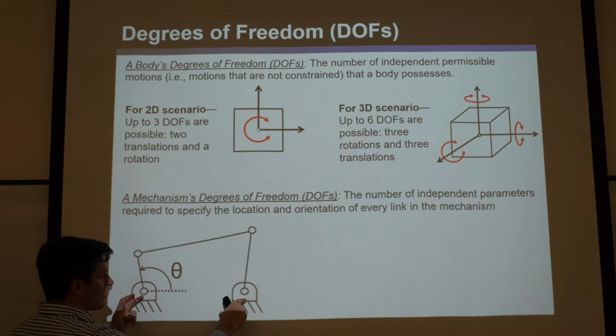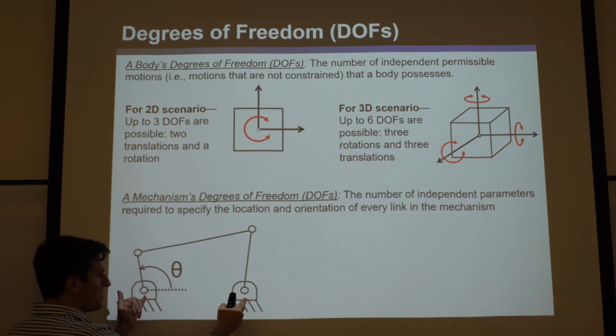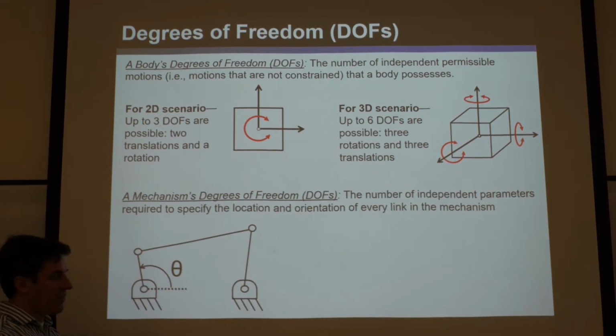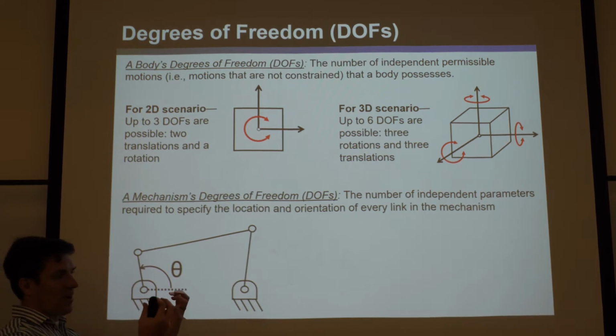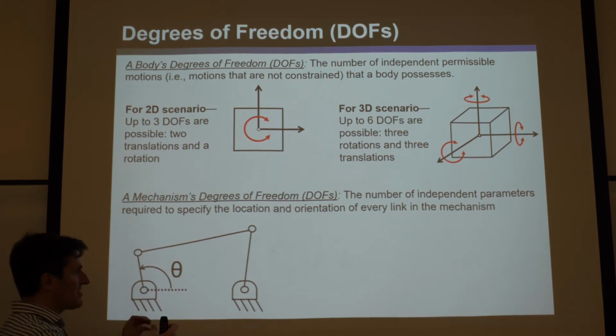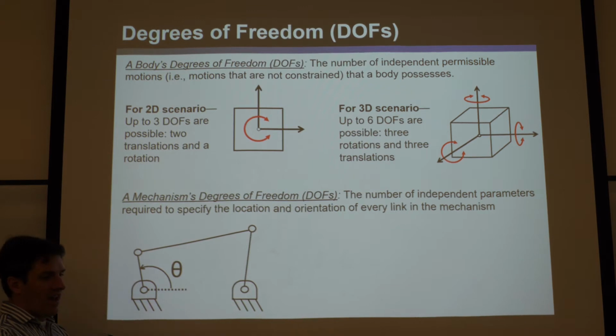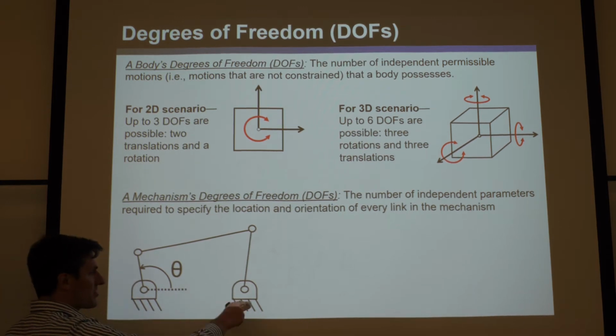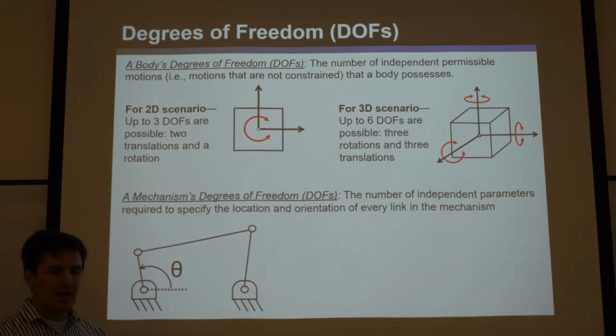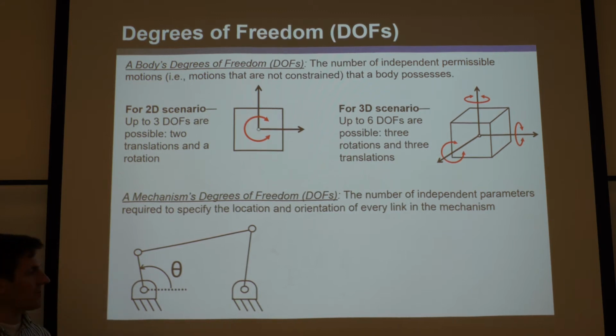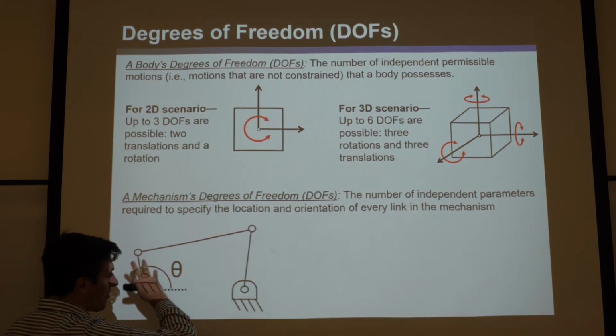See, this includes, you might think, oh, here's 2 different grounds, but one very important point, if you have 2 different grounds, they're one and the same body because they're both not moving, and they might as well be connected together as one single link. Okay, so if you see a bunch of different grounded points, you can treat them all as one single link because they might as well all be connected. They're all not moving, and all the points on them are moving with the same relative speed, which is 0. Okay, so this is 4 bodies connected together.